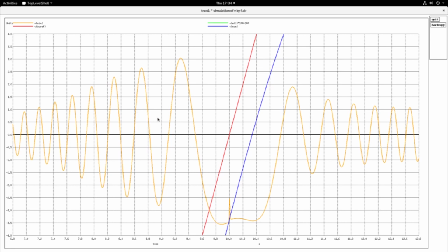So this is in the negative zone when the speed is negative, and here you have the phase change, and it goes to 180 degrees change in phase, and this is the positive, omega positive. So the phase sequence of the three-phase waveforms will change from negative to positive.